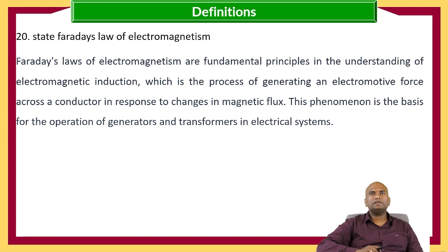This phenomenon is the basis for the operation of generators and transformers in electrical systems. That means whenever a current carrying conductor moves inside a magnetic field, an EMF will be induced. That is nothing but Faraday's laws of electromagnetic induction, and that EMF is directly proportional to the rate of change of flux linkages.